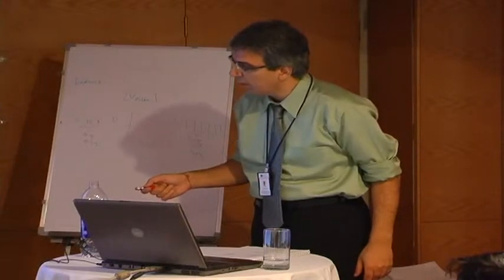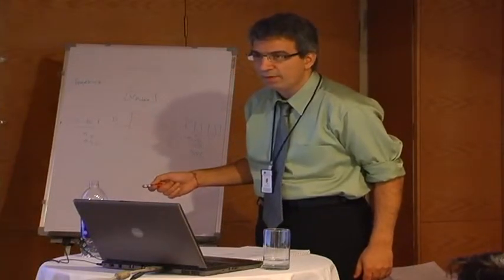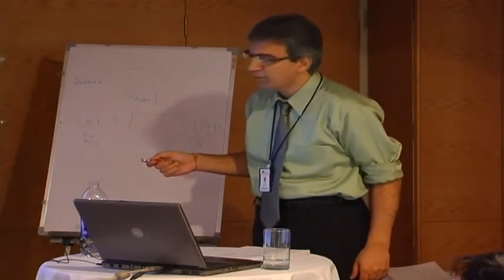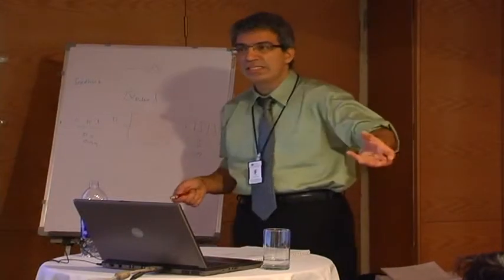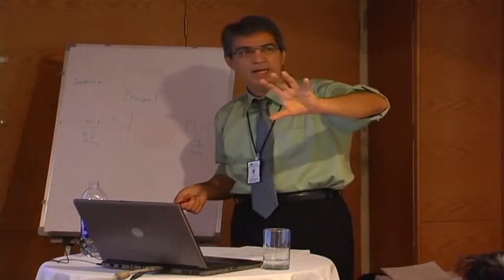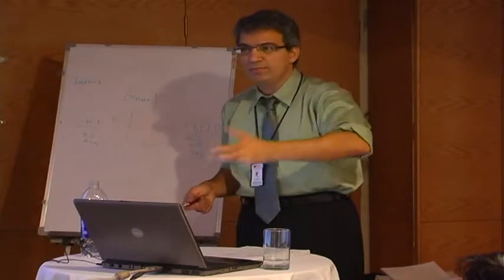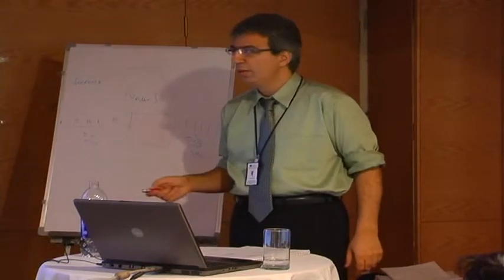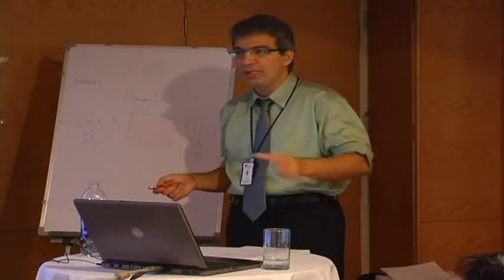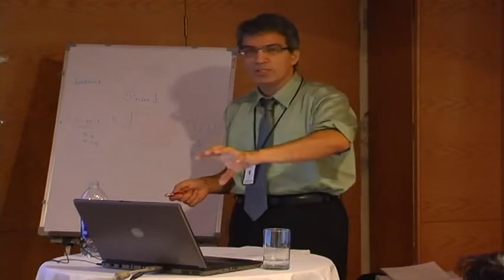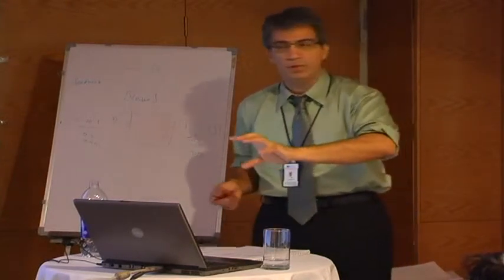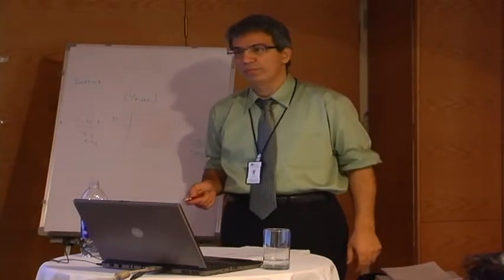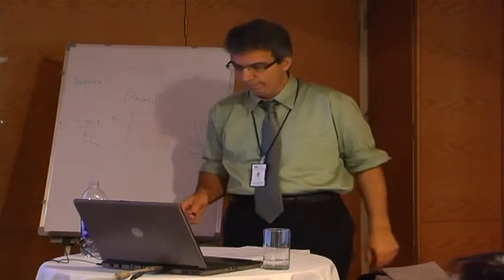This current may go like this, and when it goes like this, what happens? That means I cannot establish these currents and these currents. So the motor has a terrible lag, the current has a terrible lag, and as a result you have very poor power output. Your motor may not rotate at all. So the switching strategy has to match your type of motor. And this way, at least on Spice, you can verify how well your motor is going to behave before you pick a strategy.